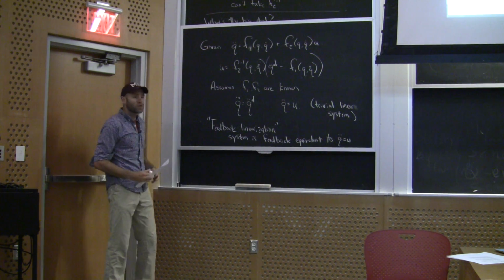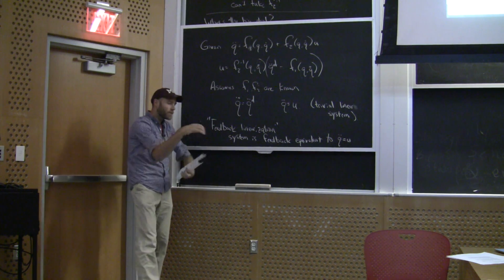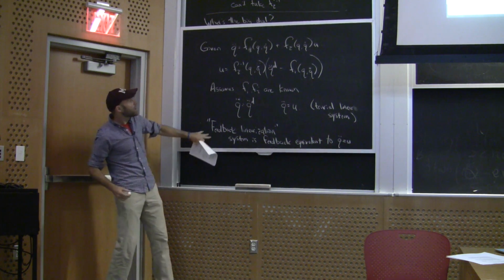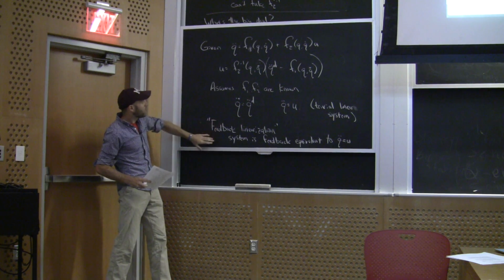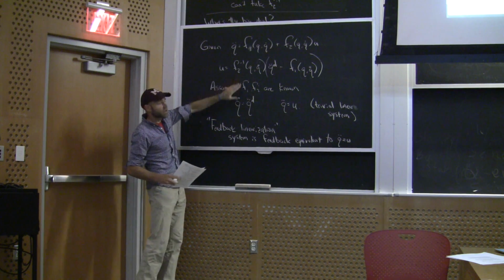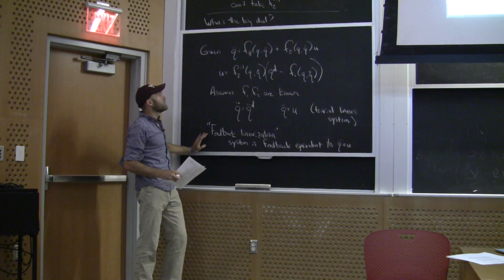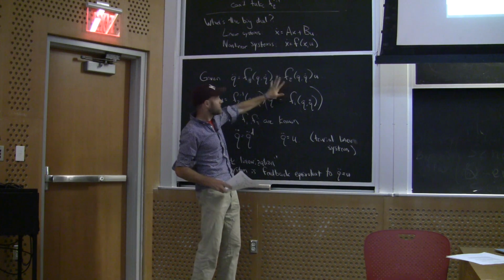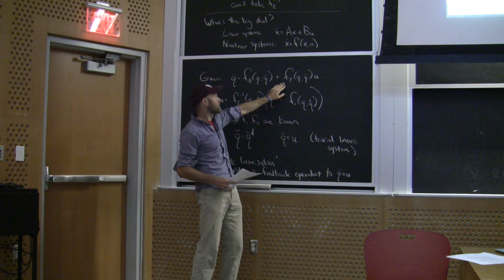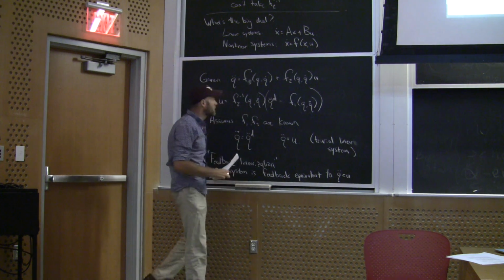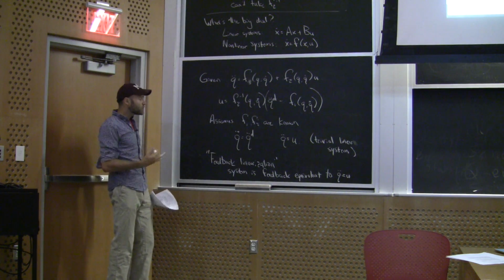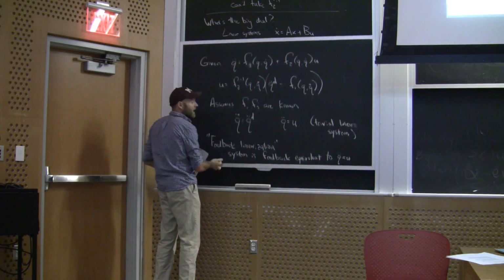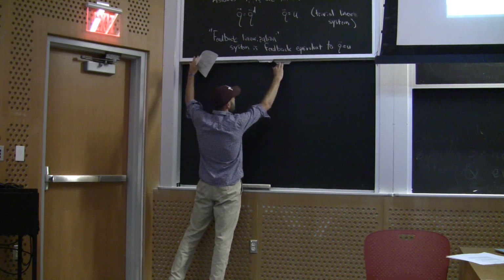Okay? So, long story short, let me wait and tell that story with the manipulator equations. Okay, so there are other things that can break this, taking this inverse, that can break feedback linearization. Having F2 lack rank is one of the simple ways to do that. If F2 is not full rank, and we'll show you examples of that, how that plays out. You can also break the ability to do feedback linearization by having other types of constraints in the system.